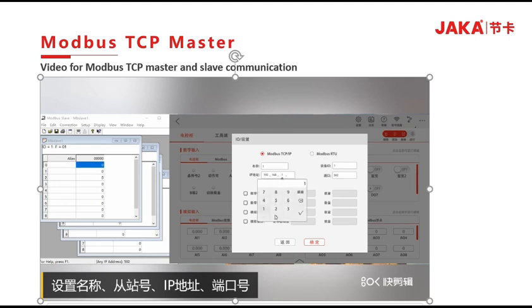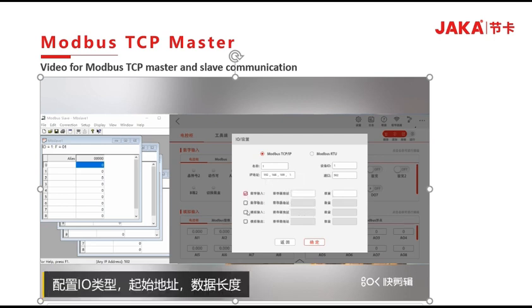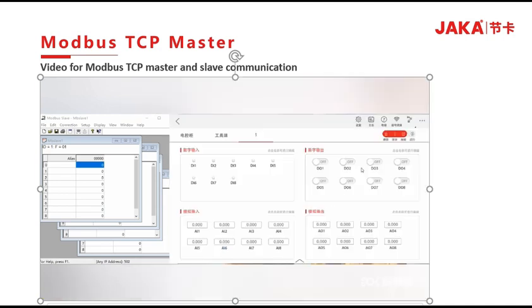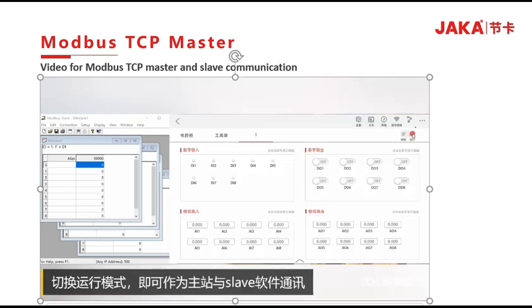Same as the Modbus slave software. IP is the same as the Modbus slave IP. Configure the DI, DO, AI and IO starting address and length. All quantity as 8. In case no error has occurred, it means our Modbus master connection is established.